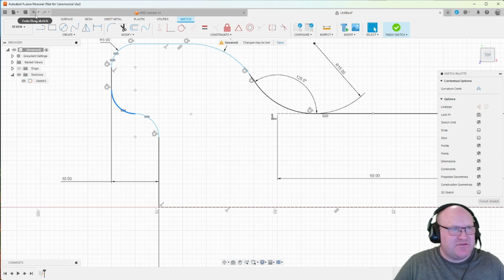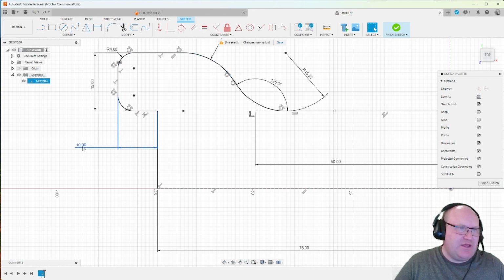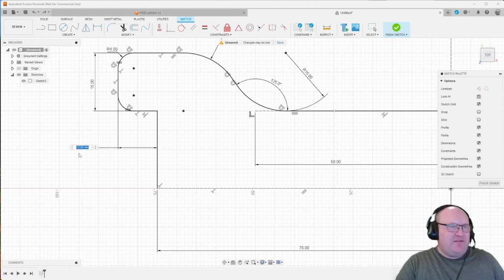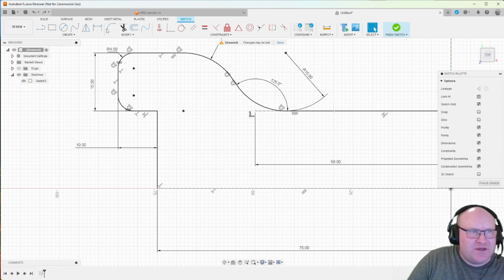So in this case, we will have to either select this point up to here, which is completely okay as well, or we will have to undo, and we should, for example, add maybe either 1 millimeter here, or we make the fillets smaller. One of two. In this case, I'm going to make this one 4 millimeters here.